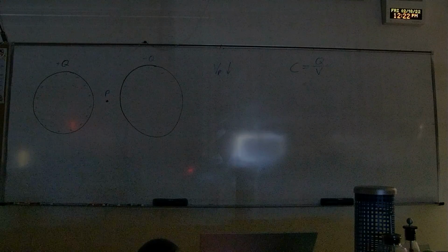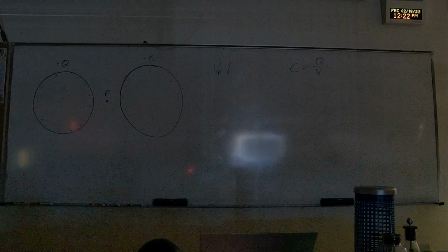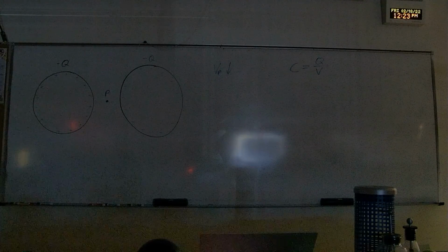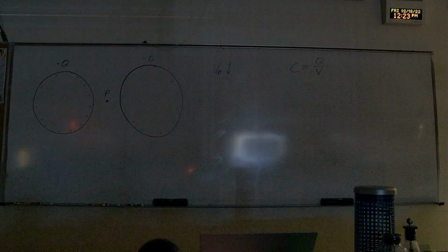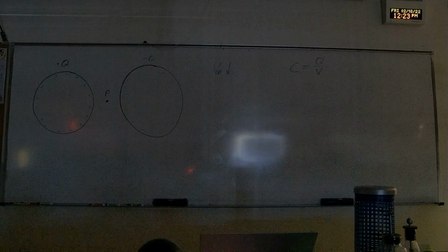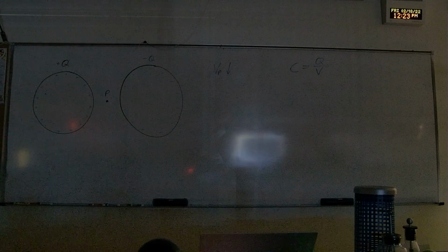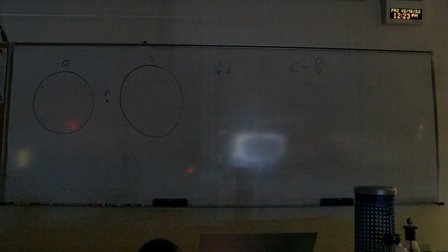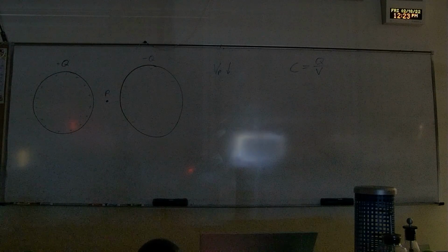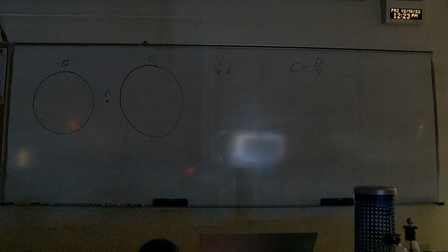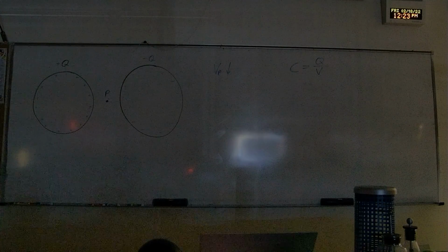So I increase the capacitance a little bit, but not much, and not to an amount where when it discharges, it's going to have a big, thick spark. For that, I need to significantly increase the capacitance. And now I can store more charge. So when it discharges, I see more charge being discharged as a much larger spark.